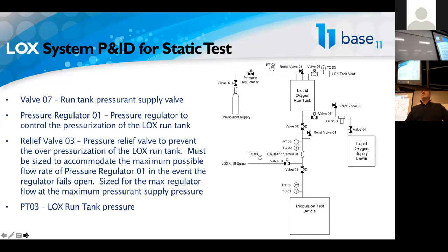Yeah, another really interesting factor with nitrous oxide is that it's an amazing solvent for hydrocarbons. In fact, there's been some recent studies that have suggested it's one of the best known solvents for hydrocarbons. So unlike something like liquid oxygen, where if you do have some contamination in it, obviously this is a dangerous situation, but it's at least not going to tend to dissolve in the LOX, whereas with nitrous it can.